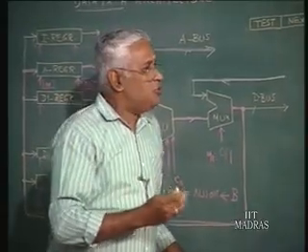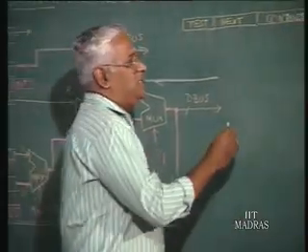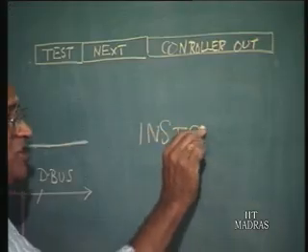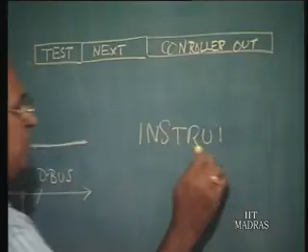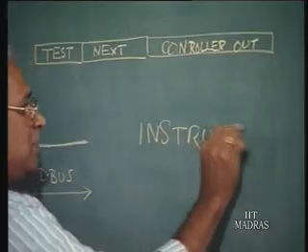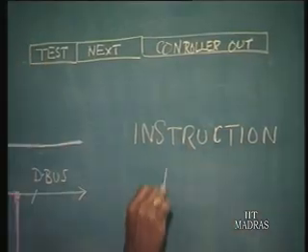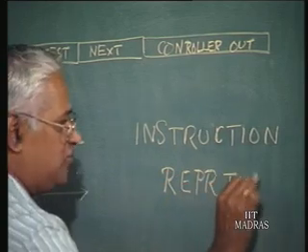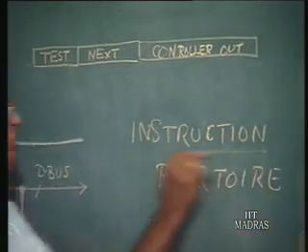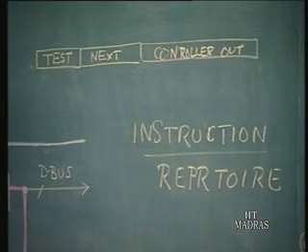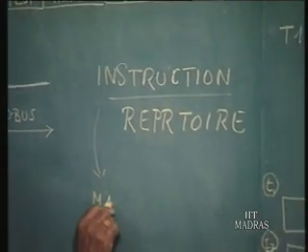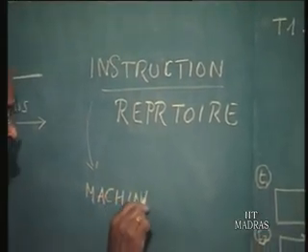Now this must be worked out for each state for all the machine cycles, which means for all the instructions. So the CPU design, as I was mentioning in the previous lecture, starts with getting the instruction set, sometimes we use this word instruction repertoire. That's nothing but the set of instructions for a CPU. Then each instruction will be worked out having the necessary machine cycles. How many machine cycles?